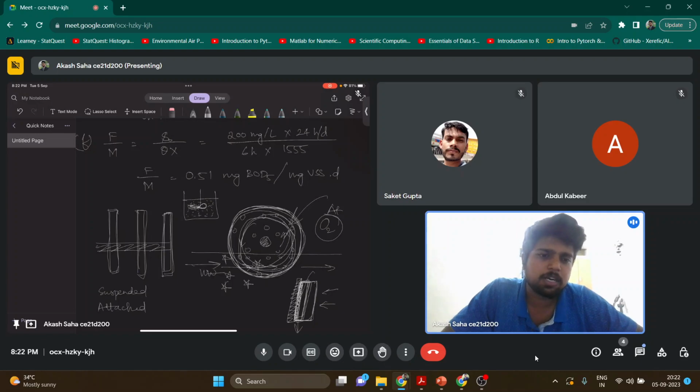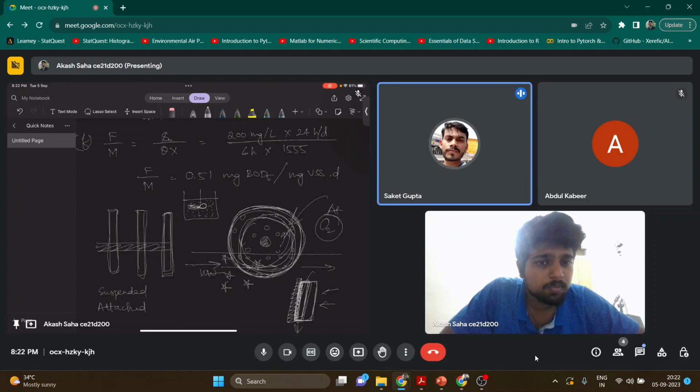So we have to subtract it from the total oxygen requirement because that part is being utilized to oxidize the ammonia nitrogen into nitrate nitrogen. So we calculate the nitrate nitrogen in terms of TKN, organic nitrogen, everything in terms of TKN. So that's why it is 4.57, that is the coefficient into the TKN. Is it okay? Sir, N naught and N will be given in the question. Yeah, surely.